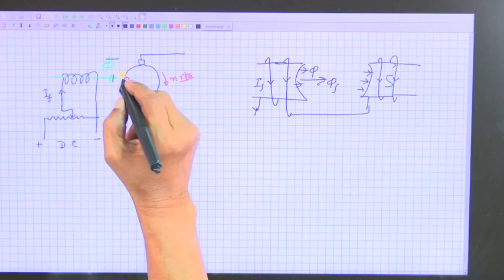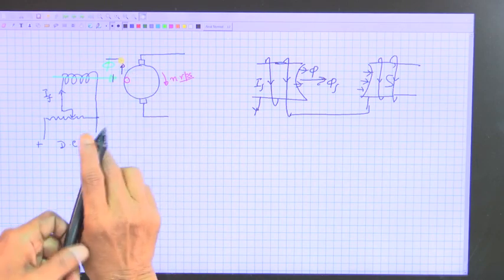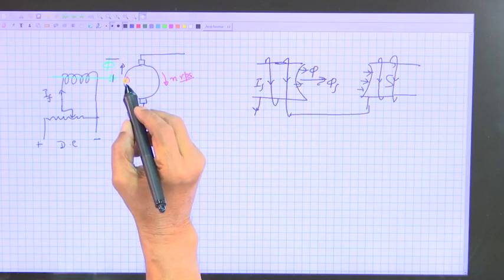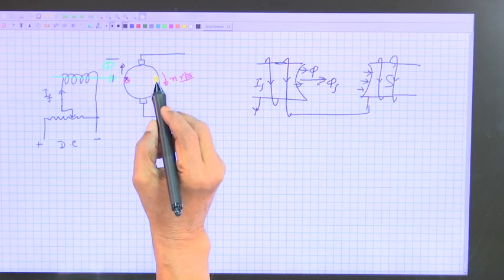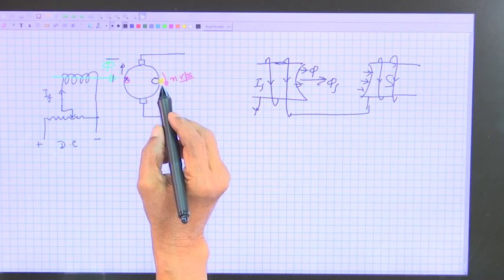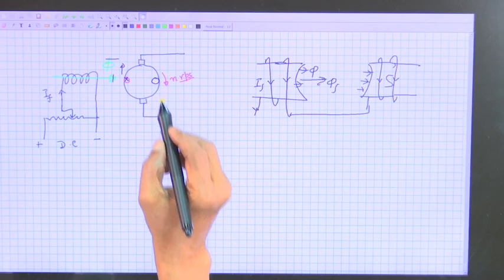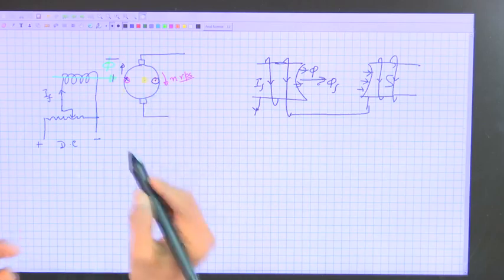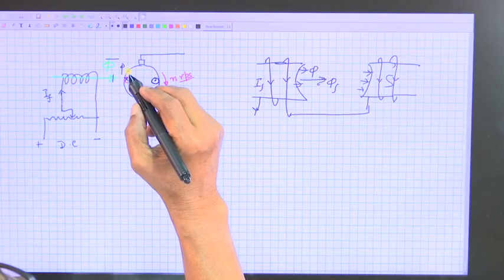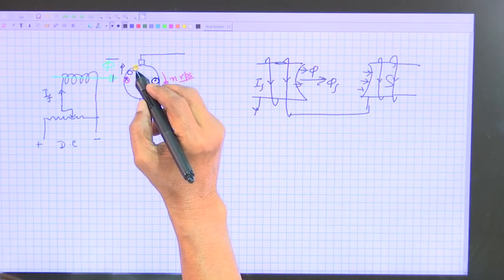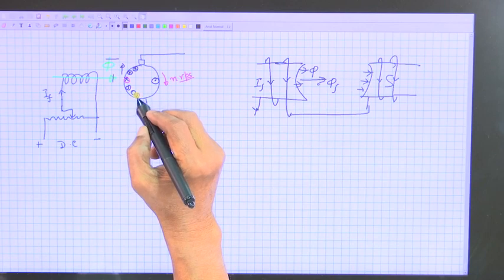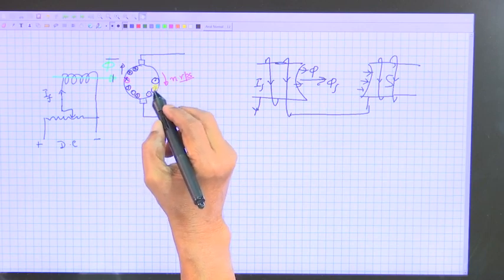Velocity for this conductor is in this direction, V, it will be cross, is not? It will be cross. And you can be rest assured, if you apply the same rule, velocity is same, but it is under south pole, it will be dot. This is what, and for all the conductors, whoever is here, that will be cross only, is not? And this will be dot.